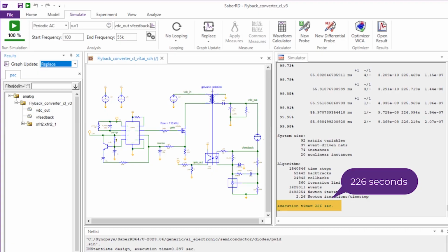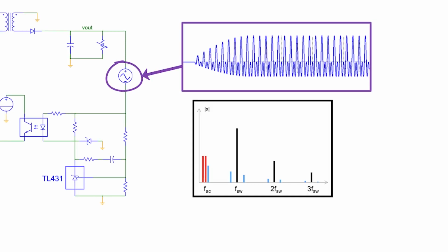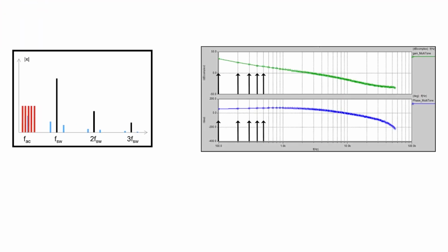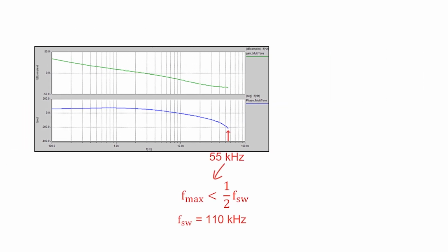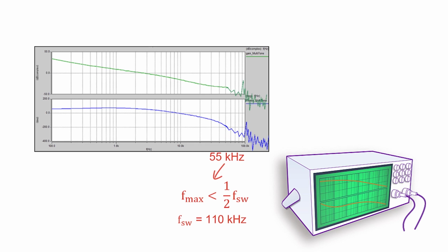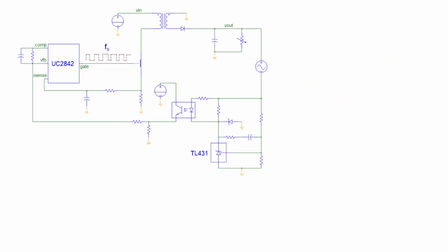There are certain drawbacks though. In multi-tone AC analysis, the tones are constructed as multiples of the start frequency of the spectrum, which necessarily leads to fewer points on the low end of the spectrum. Also, the range of the spectrum cannot exceed half the switching frequency, otherwise spectrum folding happens and with that noise. That said, this does not constitute a practical limitation since stability criteria are usually looked at below half the switching frequency. Something of more concern with multi-tone is the amplitude of the perturbation, which is a trade-off.